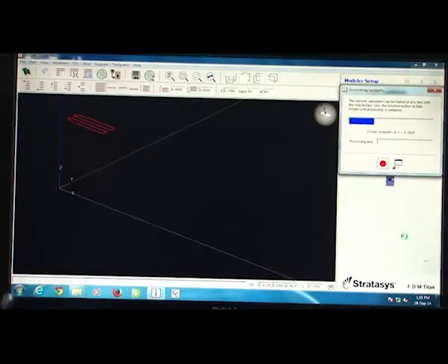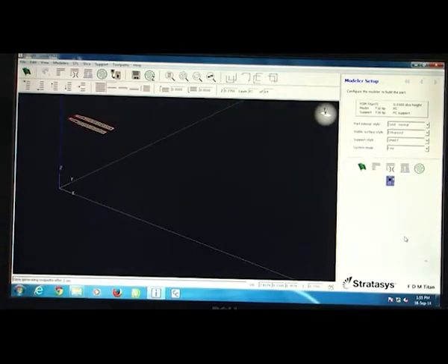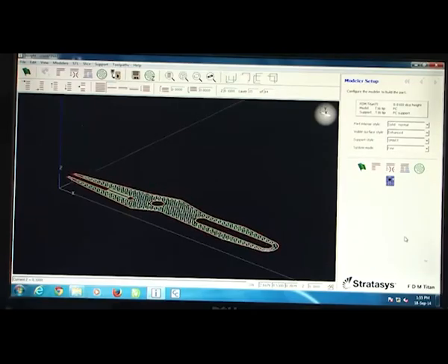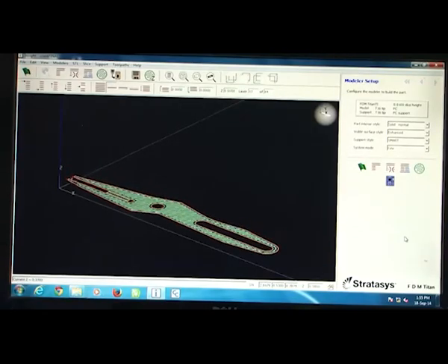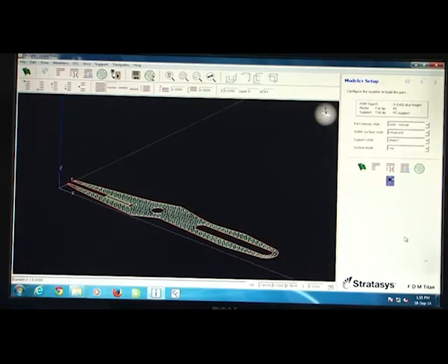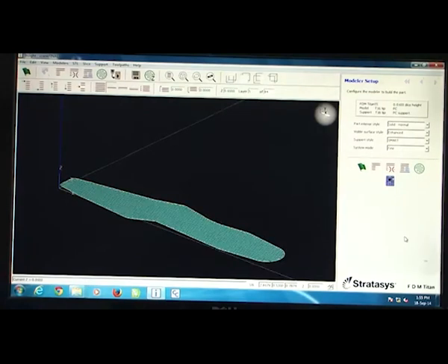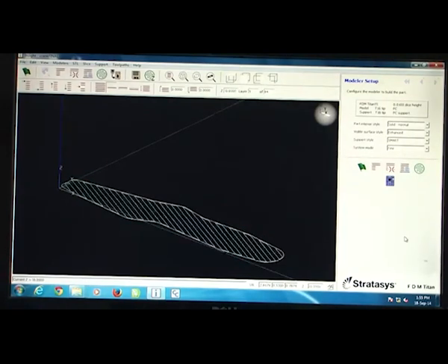So the software now tries to compute and create a layer by layer tool path, so that you can easily look at by going to the various layers how the tool paths are varying, and the green actually represents the tool path. So you can see that how the different layers are having a certain tool path defined where the nozzle would actually do the dispensing action. Okay. And typically, that's how the whole system is based on. So this is typically the support structure.